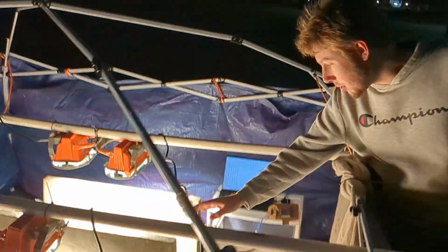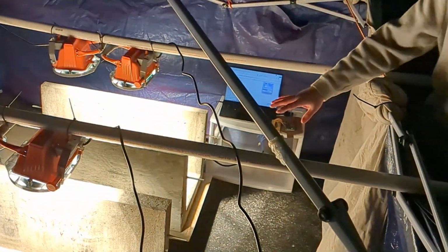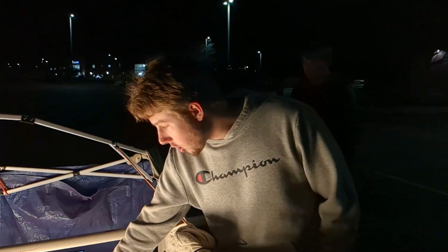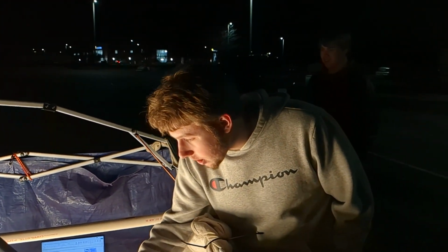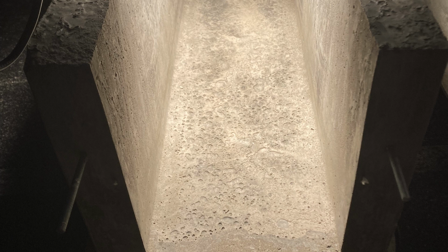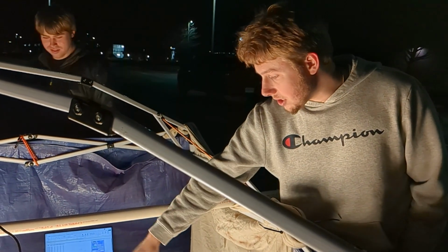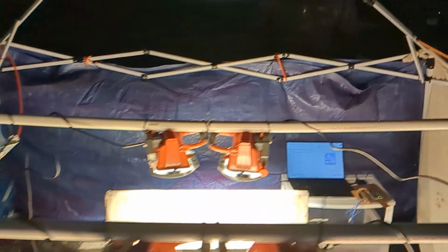All right, so to give you a little bit of information on the concrete that we got: we took both of our forms and used an orbital sander, like you would use for painting a car, to vibrate the forms. That way we could get most of the bubbles out. As you can see, there was some air trapped underneath the metal inserts in both forms, a little more pronounced on the straight walled structure because we did not really know what we were doing with the concrete, and we made it a little bit wetter. The angled wall was our second one, and we knew what we were doing.